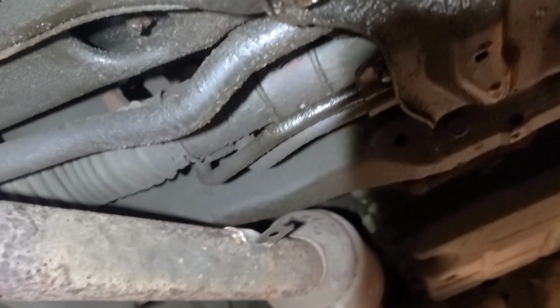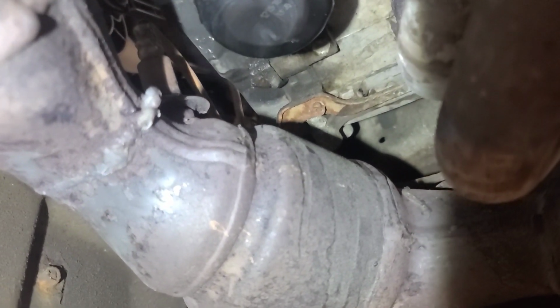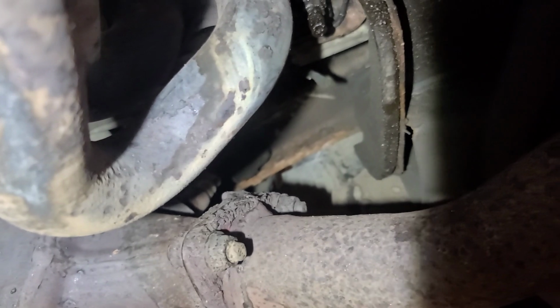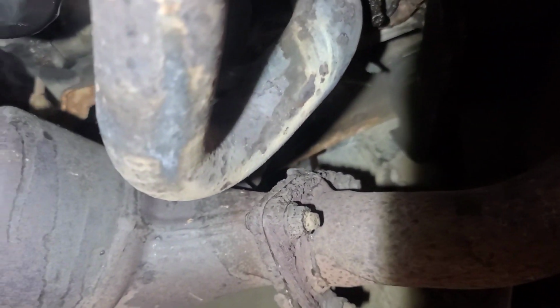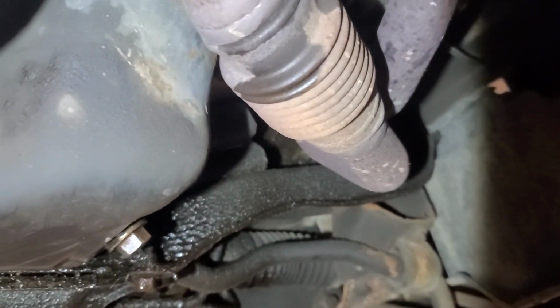So, given this thing is a little long in the tooth and it's potentially got a catalyst efficiency code anyways, because that was in history, putting an air-fuel ratio sensor in it is not going to make it run any better than it is right now. All it's going to do is enable the catalyst efficiency monitor, and after 2 drive cycles it'll turn the MIL on for that instead. So that'll disable the cruise control and the AC, well, not the AC, but cruise control.